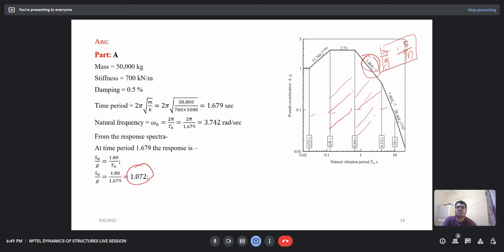Okay, directly we can use that value itself. Yes, you don't need to do the 2.71 step. That is a slope, which would be needed if you had only that line given and didn't have the value of 1.8 divided by Tn. Then you would need to go from this 2.7 point and iterate, but here the slope value is given to you.